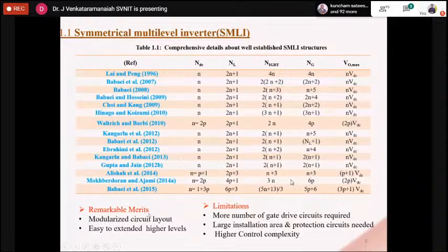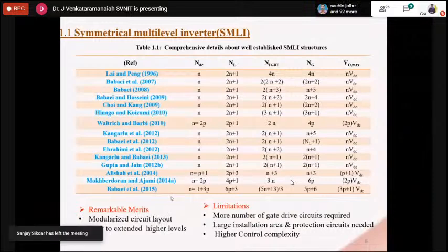So what are the remarkable merits in symmetrical MLI? Modular nature. All the modules have the same ratings, so you can easily replace them. So a modularized circuit layout is there in SMLI, and it can be extended easily to higher levels.